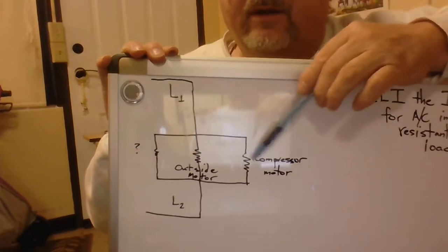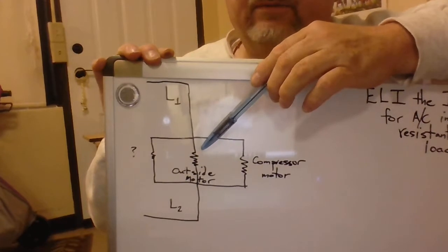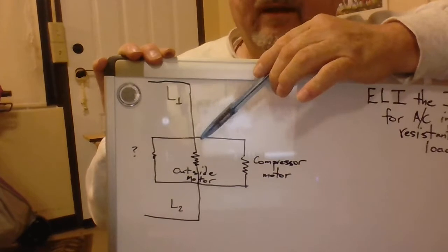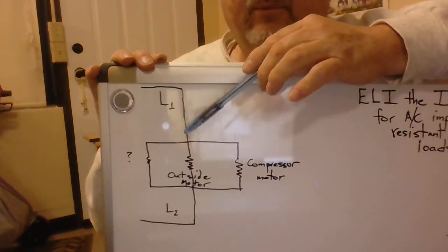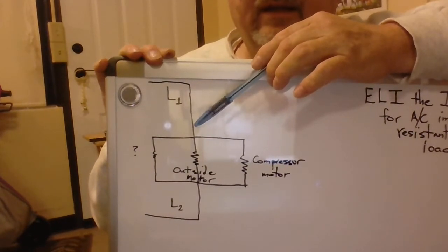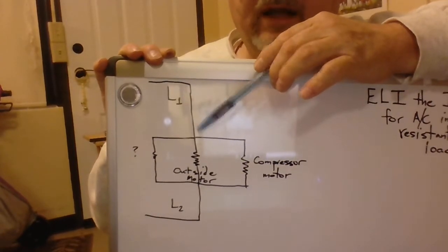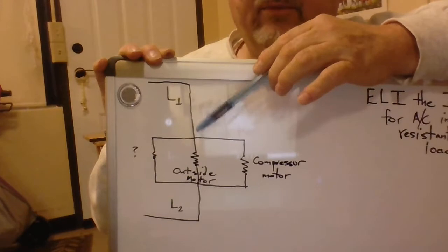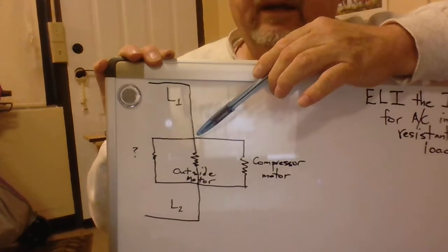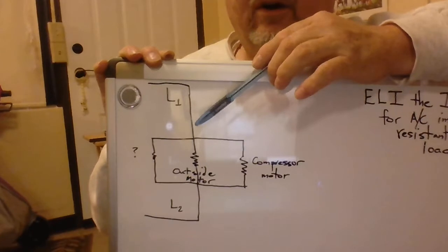The compressor dropped down to the full load amps, and the outdoor unit was running under its run load amp rating as well. I explained to the customer that we got the root cause of what the problem was, and went ahead and left the new motor in because the old motor was most likely irreparably damaged, having run in that condition for quite some time, because it would heat up and cut off, and then the compressor would run without a condenser fan motor, which is not a good condition at all for anything.